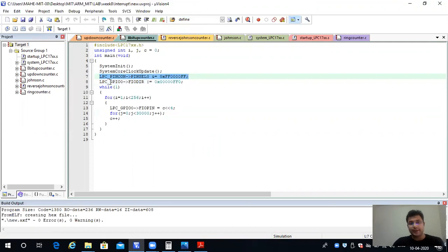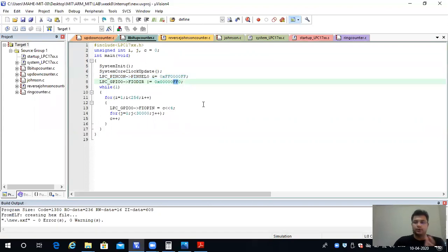Then we want to set the direction, obviously from the system perspective, because the system will put values over these pins. Those pins which we have configured as GPIO pins are output pins. So for pin number 0 to 11, it is FF. The direction is set as 1, which means the output direction.